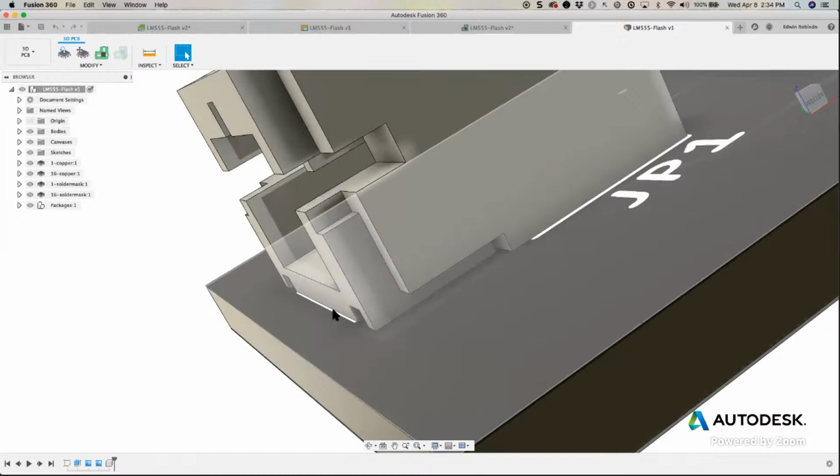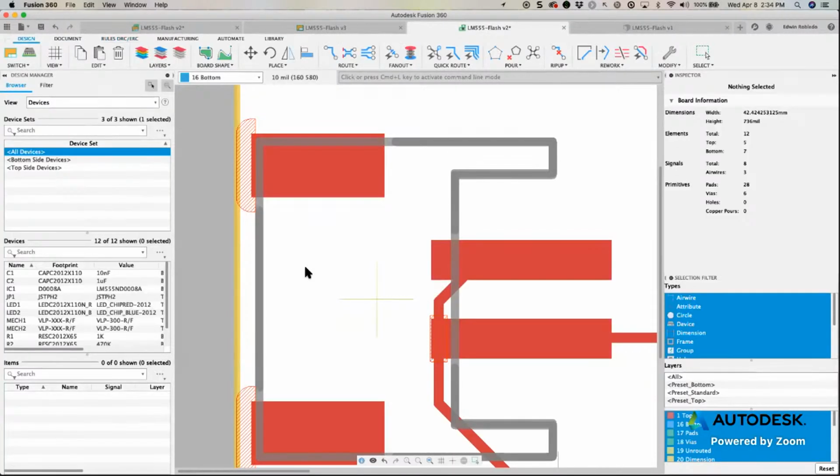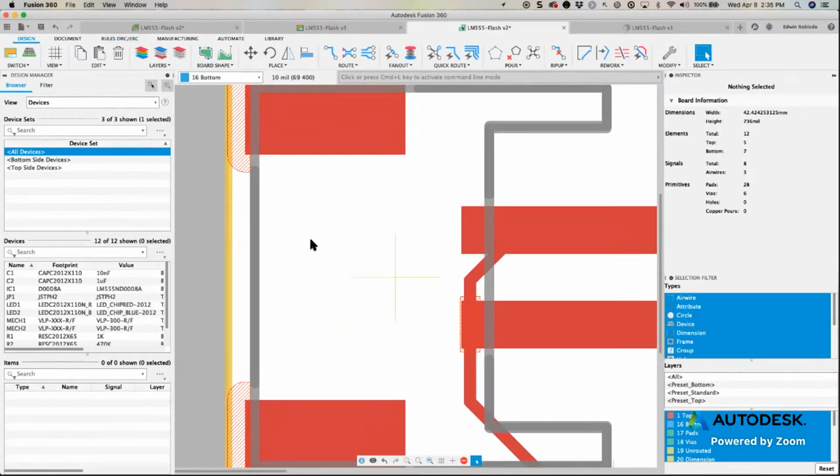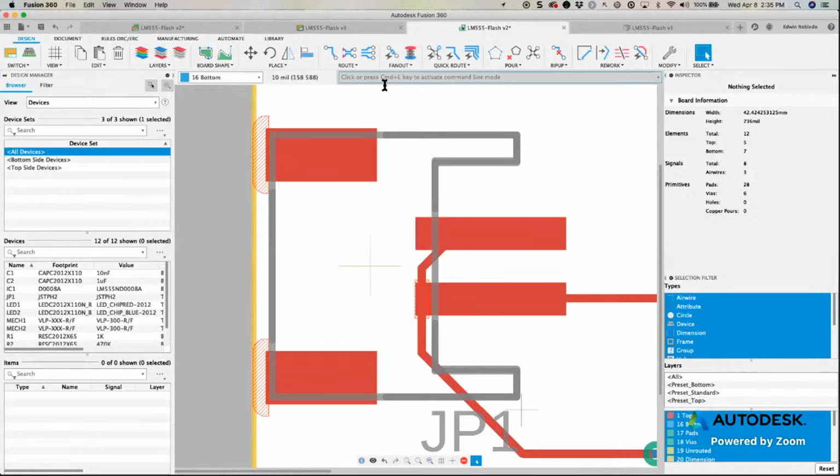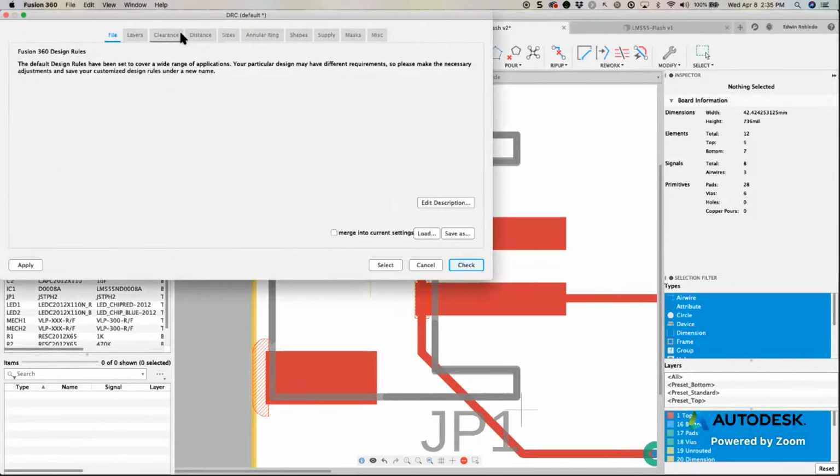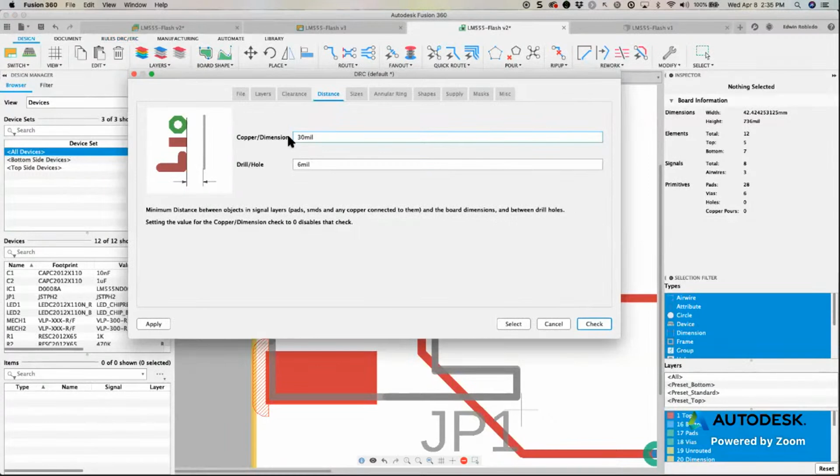So I might move it forward to this edge, that way it's easier to plug. But it lets me do it. It's just kind of telling me, look, if you leave it there, you're violating your DRC setup for the board edge as well as anything that has to do with copper. So you'll get the same flag if you do any traces below that.